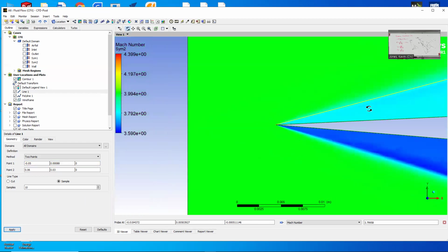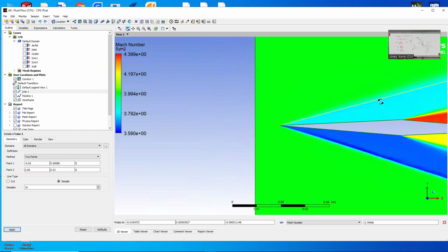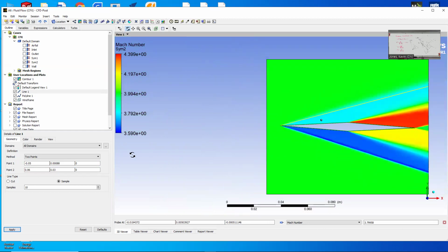And then what you'd want to do, this top one's actually harder than the bottom one because it's a little bit more spread out. Hunt for something that looks like it's pretty close to the edge. It'll add a third dimension to it, but I guess you don't care here. Yeah, and then you would basically do trig on these numbers and find the angle. So that's a good way to, if you want to try to compare the angle to what you get out of the PT calculator. There is, like I said, some uncertainty here because I don't know if I'm putting it exactly where the shock is.